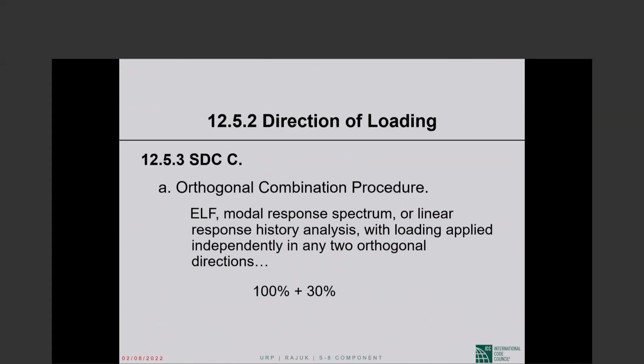The first procedure is the orthogonal combination procedure. Equivalent lateral force, modal response spectrum, or linear response history analysis with loading applied independently in any two orthogonal directions.